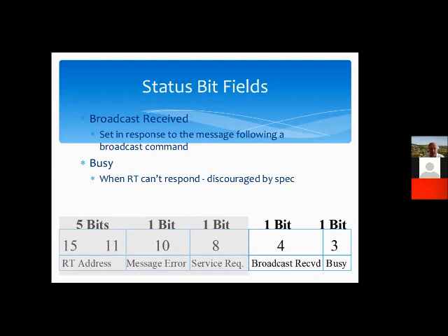Dave? Yeah. I have one more question here. Regarding broadcast, is broadcast to all sub addresses in a single RT possible? No. Within a broadcast message, there is a particular subaddress in the command. Okay, thank you. Okay.